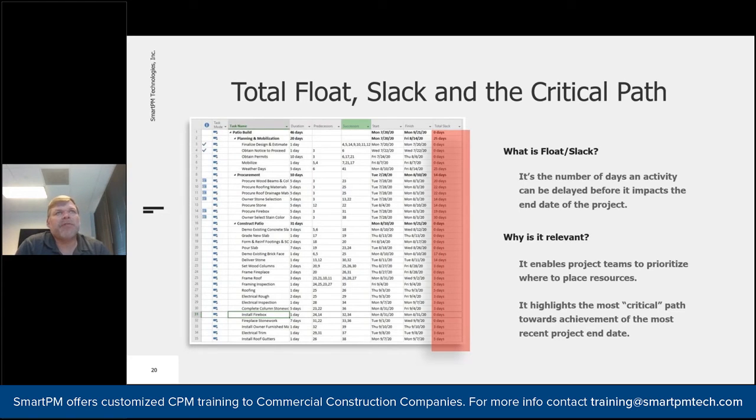And that will enable you to make better decisions. For instance, if something is going to be extremely late delivered and there's nothing you can do about it and it's a critical path activity, well, we've got to start thinking about how we manage with that reality in mind. It could be a discussion. It could be completely resequencing the work. For instance, a certain bit of structural steel is not going to get there on one side of the building, and you can start on the other side of the building instead.